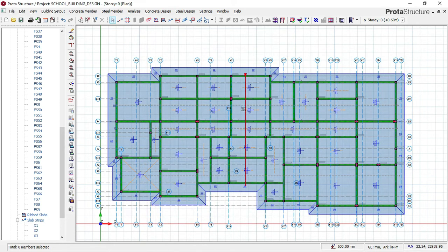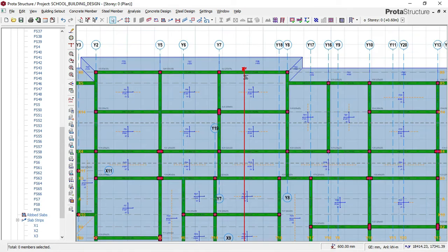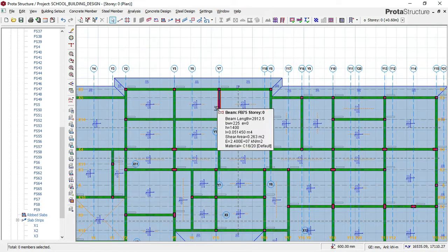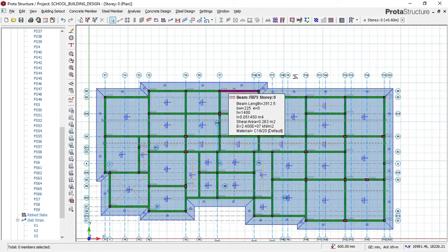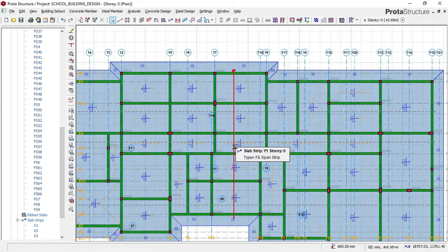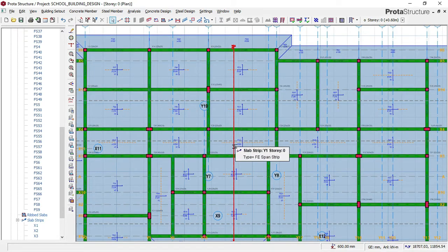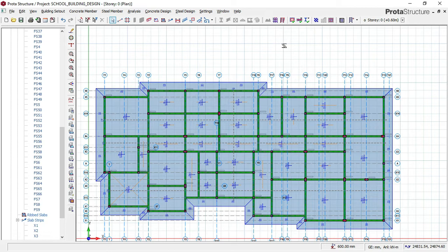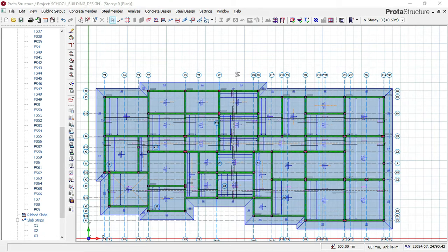Once you close, you can see that we have already done the strip. Since we have already designed our slab foundation, we can right click here to see the Raft Foundation reinforcement slab. We can right click here, go here and say update T-bars. Wait for it to finish. It will take a few seconds to show the T-bars. Once it is shown, we can move on.